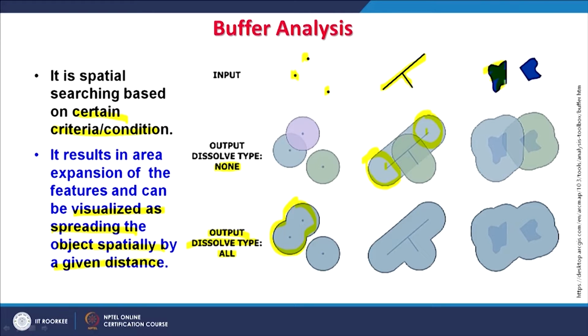Similarly for polygon, the same way it can be done, and this width which we are talking about is basically the expansion of a feature. Now, I have given one example about the pollutants. It may be related with groundwater extraction, it may be related with oil exploration or oil extraction, or any other feature, or along a road also, that we want to know who owns the land along a road, and if we want to create, say, a 500 meter buffer, then that can be created.